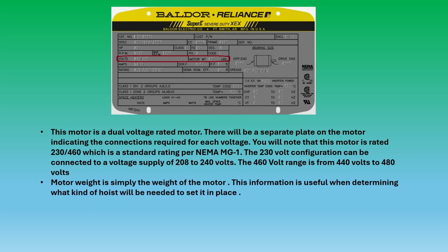Motor weight is just simply the weight of the motor. This information is useful in determining what kind of hoist will be needed to set it in place, so you make sure you have something rated for that weight.